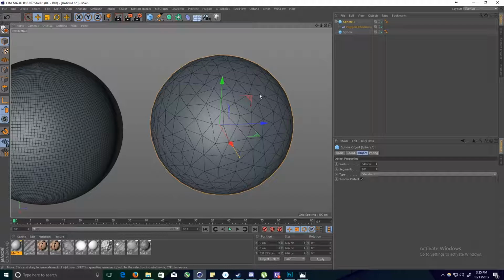If you made a texture out of just noises and a bunch of generative stuff, and then you bake that, you're taking all that noise data and saying, okay, now I just want a picture. I don't want any of this procedural, parameter stuff. I just want a flat texture. Baking would do that. What are some good textures that are worth baking? Certain materials, like fabric, are one of those. Fabric, folds, yeah. Honestly, you're going to want to bake anytime you're working in a game engine like Unreal.